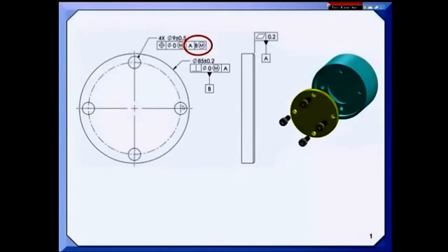It means that I will allow a shift on the datum feature in order to bring these holes into their positional tolerance. If you treat it like a bonus, you're saying that the pattern can deviate more. In other words, the holes could get further away from one another or closer and kind of destroy the pattern. So that's not what it's saying. What it's really saying is the pattern can shift relative to the datum axis established by datum feature B, as long as we maintain the pattern.